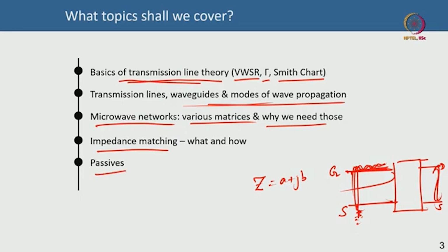And finally, we will talk about passives, and that could be also a little bit detailed. Passives are very important, because on the wafer you need to fabricate, characterize, model and enable these passives oftentimes, such as in MMIC. MMIC is a complete RF chip on wafer, on the same die, monolithically. There is no separate integration of a discrete part, everything is fabricated on the same chip.